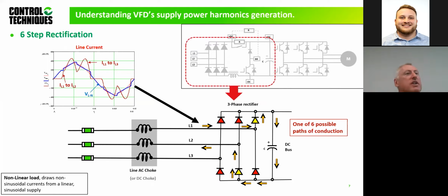But along with that, look at the voltage, how it starts to distort. It's not looking too nice, and that voltage is probably the most concerning thing when we talk about variable speed drives, or what we call nonlinear loads because the current is non-sinusoidal, which has impact on other equipment. And this is what I'll be mostly focusing on as we go along this presentation. Voltage is seen across all the equipment, but it's a product of what's generated from the current drawn from the supply. So again, you can see it's ugly. The more impedance we start adding to the line, the worse that voltage will get. So, a simple overview of the front end: diode rectifier, three-phase bridge with a capacitor. And again, most VFDs today are voltage source drives.